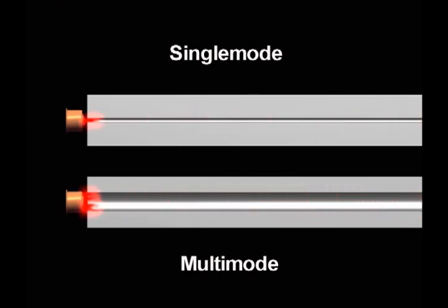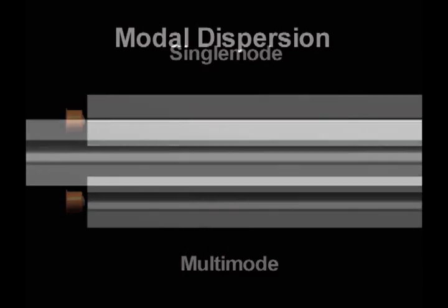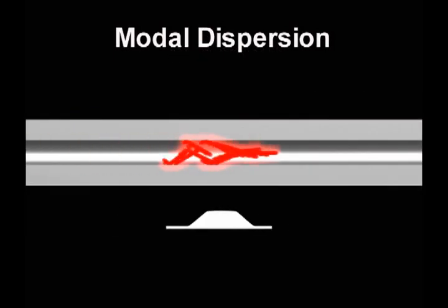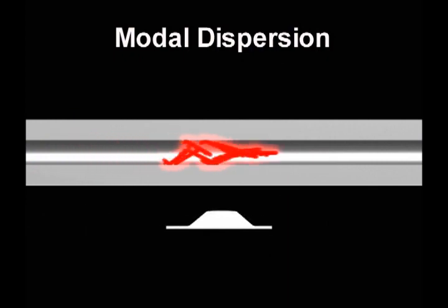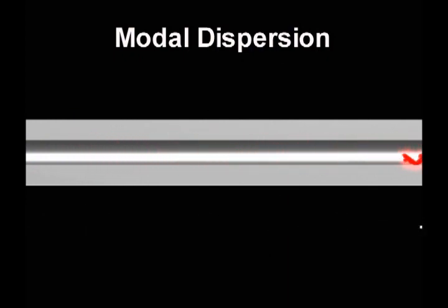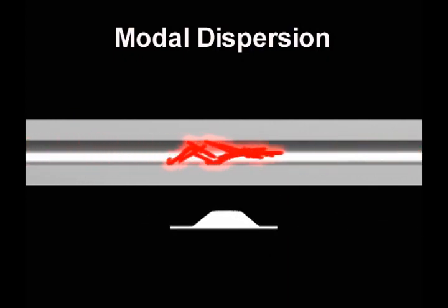at a single wavelength. Multimode fiber has a much larger core diameter, allowing light to take a number of pathways from one end of the fiber to the other. The fundamental mode travels down the fiber axis, while higher-order modes will take a number of longer alternate pathways. When a short pulse of light is launched into the simplest type of multimode fiber, a step-index fiber, the fundamental mode arrives at the other end first, followed by the higher-order modes.